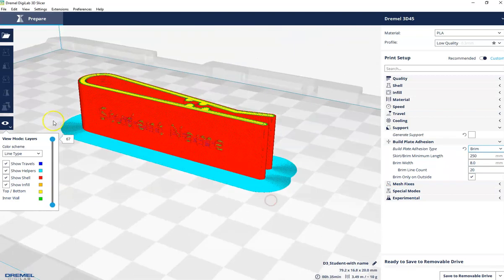And this is common and needed depending on the part and the materials, because sometimes what will happen in large prints is the parts will start to come off the build plate and then we'll get kind of a bird's nest because the part will lose alignment.